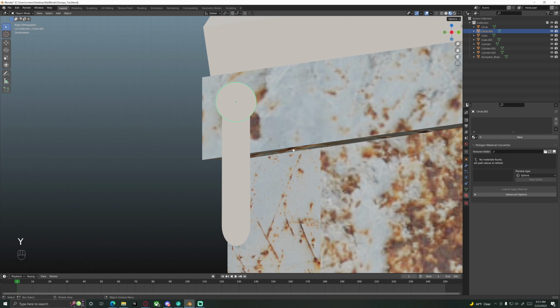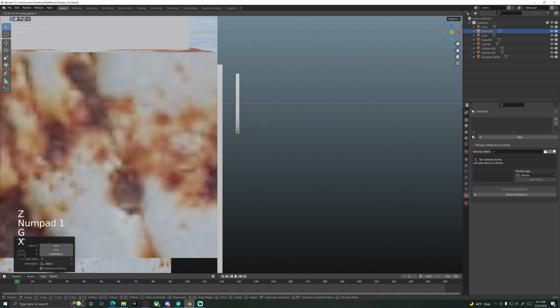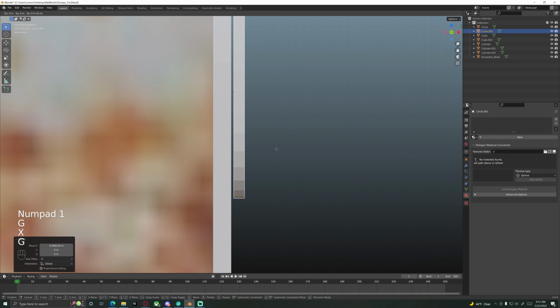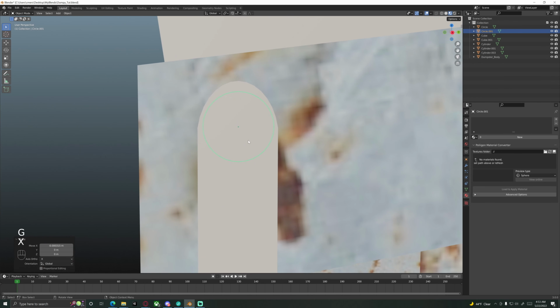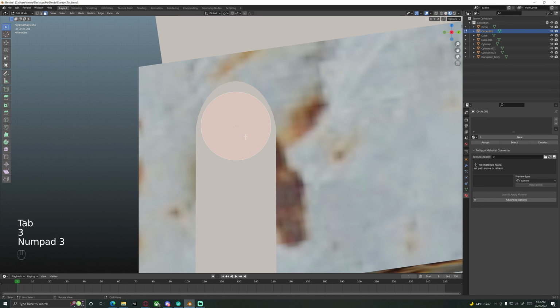Yeah, so then we'll grab our circle that we duplicated here and we'll just scale this down to match somewhere right in here. Bring it up a little bit on the Z. Right in there seems good. Okay. And we're going to bring this over on the X and get it to just kind of meet up right up against this one here. Okay. Tab into edit mode with this front face selected. We're going to hit E to extrude, S to scale, and we're going to bring it in about...